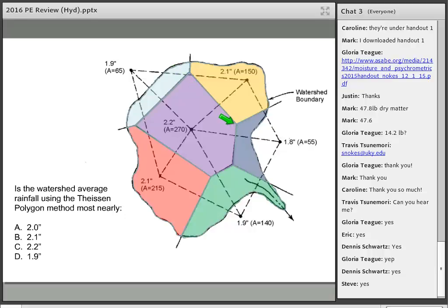And the way you construct it literally is to take a compass and scribe a line over here and then over here that is of one length, and then you take the compass to the other point and scribe and cross those points, and when you draw the line between them, that whole line is equidistant from the rain gauges. And I've done that construction then for every set of rain gauges.